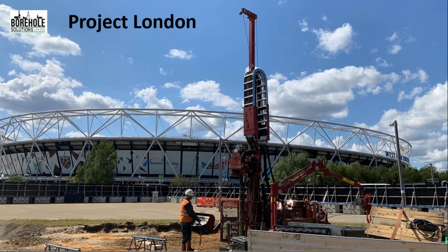And the speed as well. The speed, drilling gravels and dense sands and things, and especially the Lambeth group and the black pebbles you get in there. With the cable percussive, you could spend hours chiseling away, then shelling them out. I mean, the sonic gets through it, and you get recovery. You see what it is. You're not getting a bag of slop or a bucket of slop with a log.